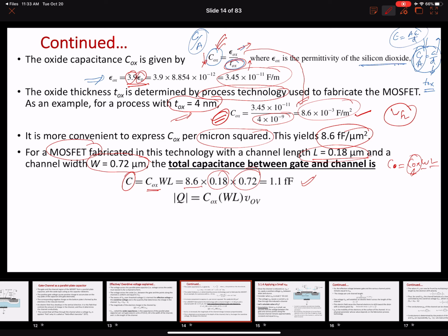In terms of the total charge accumulation by the channel, as we have talked about, we can vary these parameters. We can increase the width and the length, or increase the capacitance, to increase the charge accumulation in the channel. And in order to increase the capacitance, we have to decrease the oxide thickness. We may have different fundamental limitations in current technology on how small the transistors we can fabricate are. We're going to briefly discuss that in the subsequent lectures.